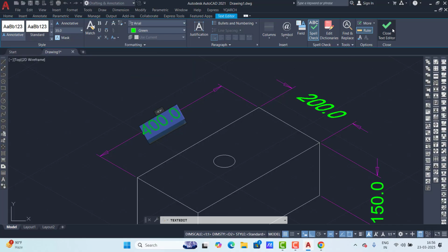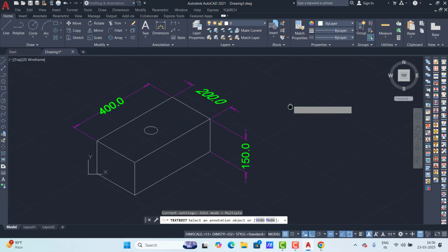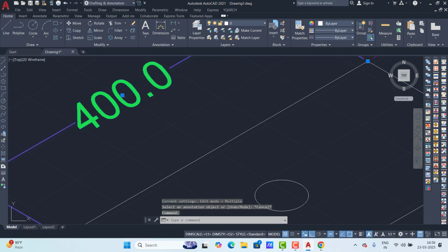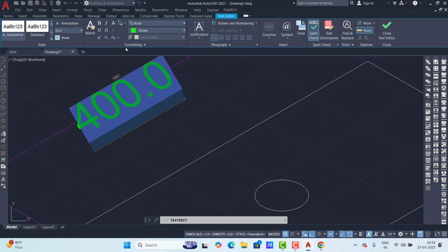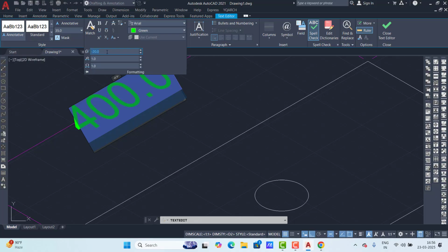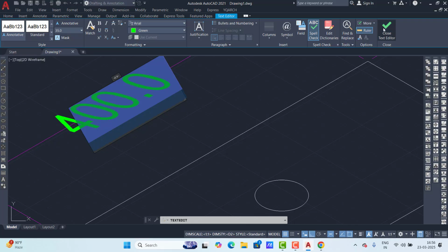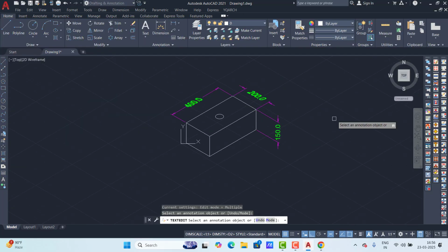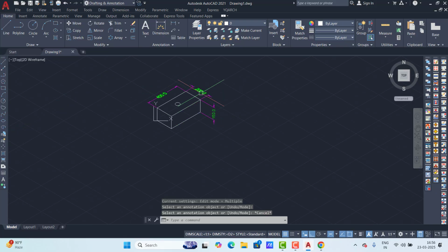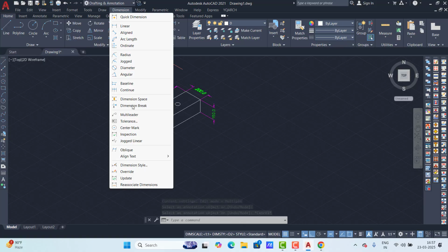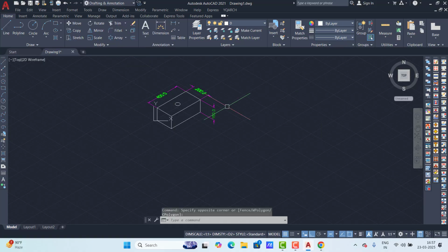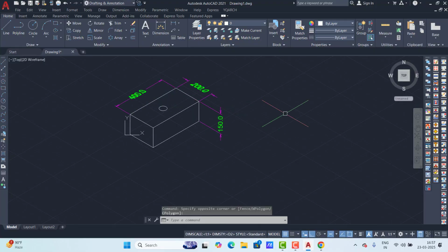Now see, center 40 this side, 40 this side, these two circle positions. So what we do? O enter, 40 this side, 40 this side. So here this one is the main center. Here I have to make two circles. Circle one is 8 radius and here see the distance is 4. So that means the outer radius is how much? 12. Okay. Now here inner is 28, 22 dia, and outer dia is not given here. Okay, so this way you have to make proper dimensions. Here the outer dimension is missing.